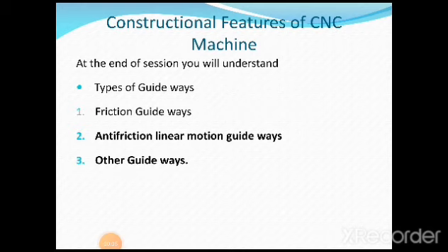So today I'll be discussing in connection with the continuation of types of guideways. Before I proceed with today's session, we need to just revise what we have discussed in the previous session. We started with the guide and guideways, because it is the guide and guideways which are responsible for giving the proper positioning, proper location of your machine table or the workpiece. That is the main function of the guide and guideways.